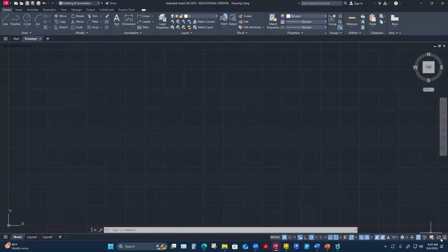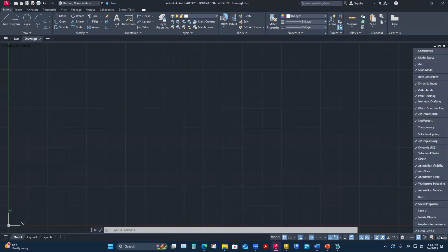But what you have access to clear over on the bottom right is another little three bars that is an expandable menu. I tell you, AutoCAD has such little icons, and the power of them is very misrepresented by the size of the icon. Some of this stuff is pretty powerful and it's buried deep in a list somewhere. But if I pull this up, this is kind of like my quick access toolbar on top. The things that are checked on mine are what I've added to my status bar. And if I uncheck them here, they just get pulled away from my status bar.